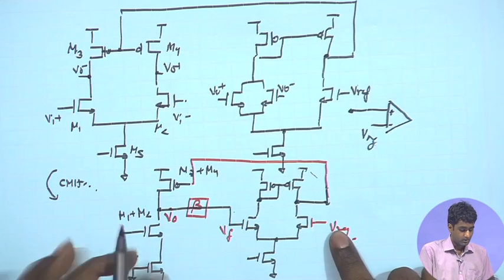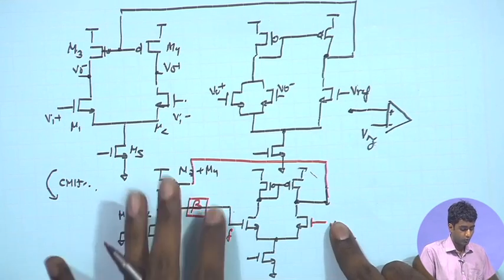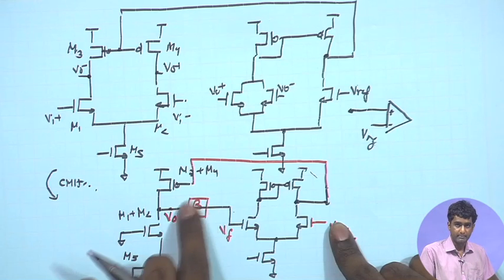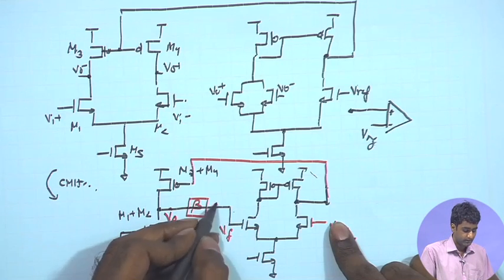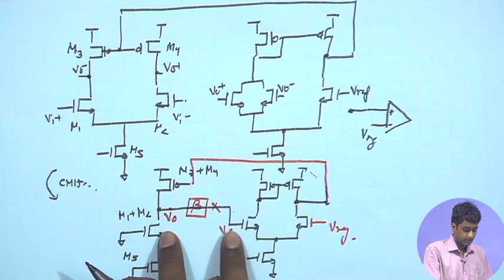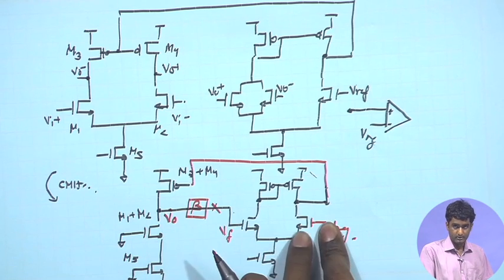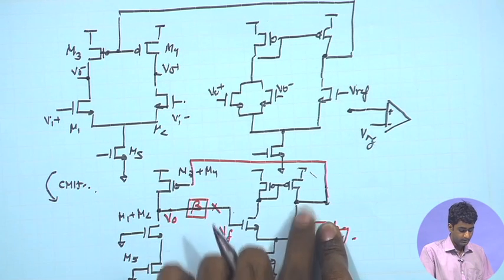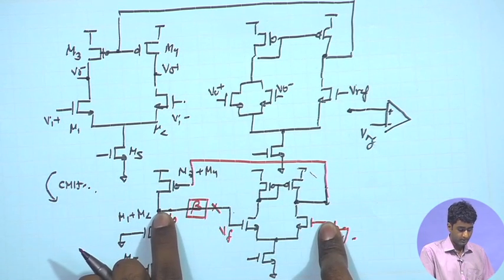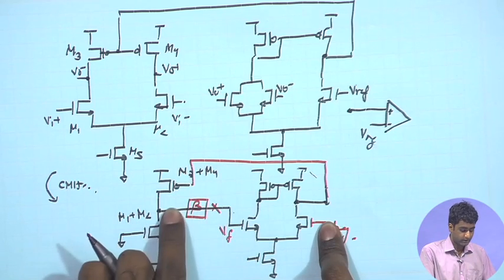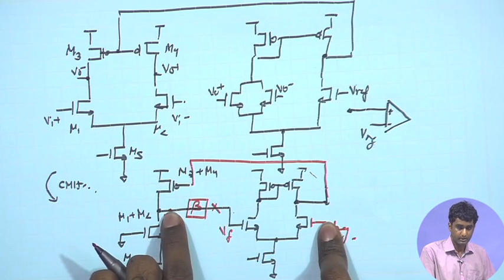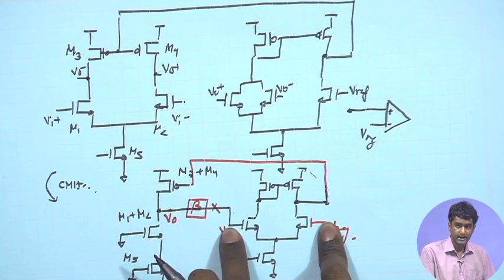So, now if we therefore open this loop, assuming this sampling factor to be unity, we can say that you are having an input signal applied at the positive terminal, you are having the non-inverting amplified voltage signal coming back, which is finally applied at the negative terminal.